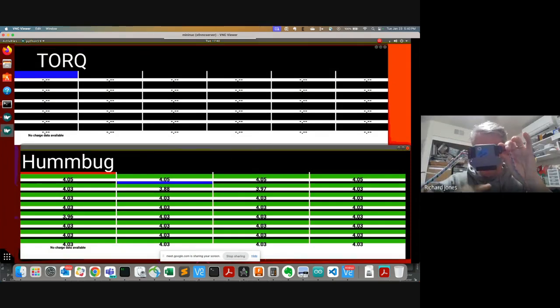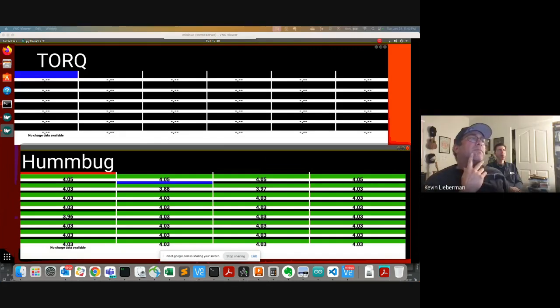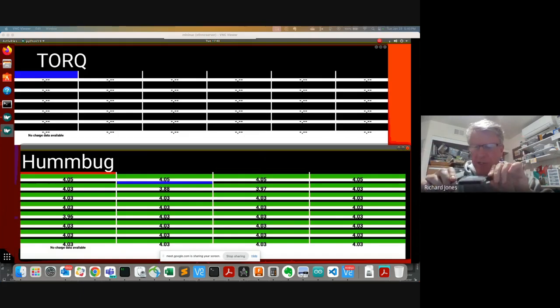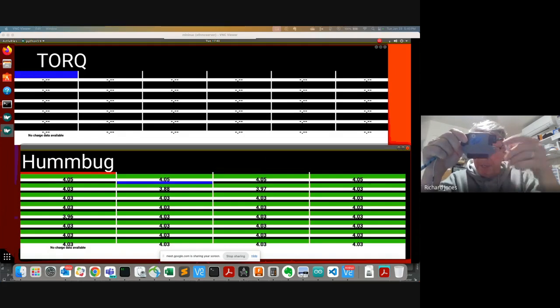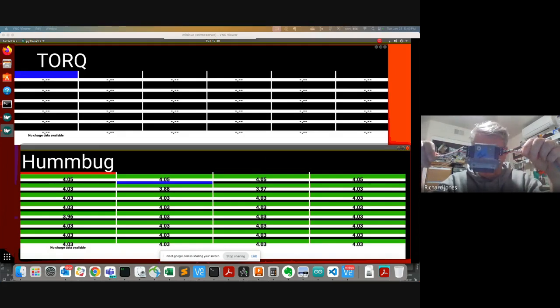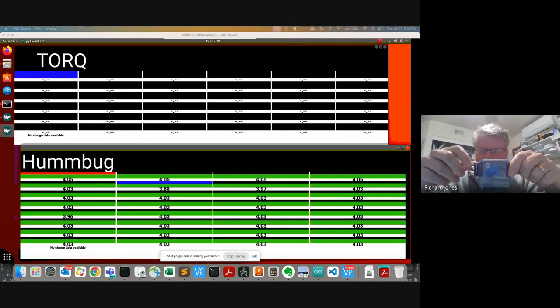Yeah, I was just going to show. This is the little BMS board that Kevin's got in his vehicle. This is the old Ziva that says 12 cells. It's kind of hard to see, but the 12 wires connect in on the bottom here. And this is the CAN bus across the top. So there's a connector that goes into and a connector that goes out of here. In fact, it doesn't really matter which way's in and out, but there are two wires which are CAN, which are twisted. And then there's power and ground, 12 volt and ground. And this is black and red, which kind of makes sense. The power wires are thicker, and the CAN wires are thin and twisted.